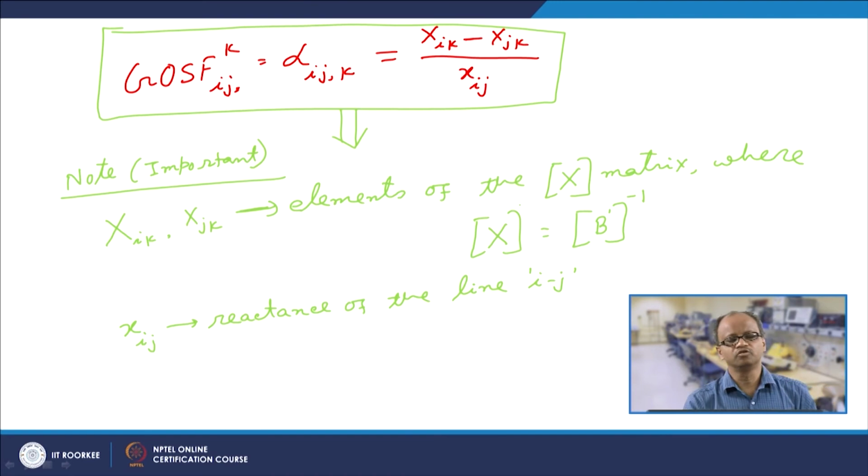So for any given system, the moment we know the line parameters, we can simply pre-calculate these values by this simple expression. Even if the values of i, j and k are very large, because the expression is very simple, it is very easy to code, and it will take hardly any time for modern day computers to pre-calculate these sensitivity factors and store them.